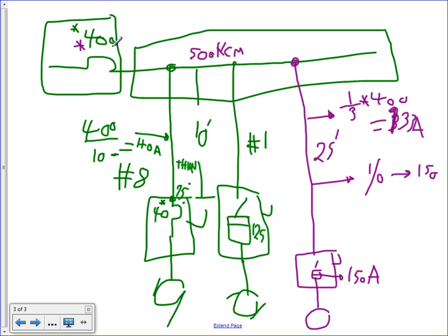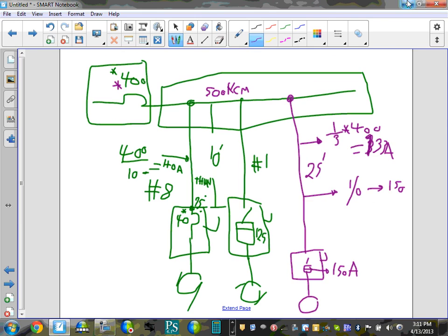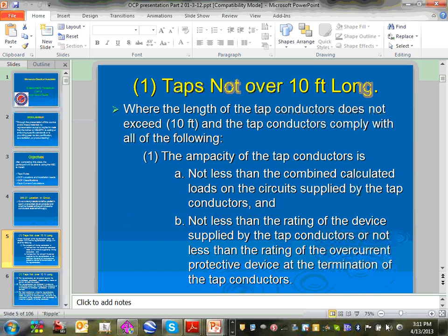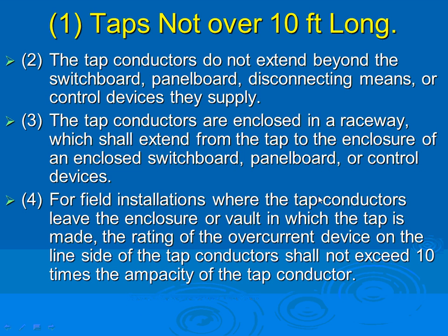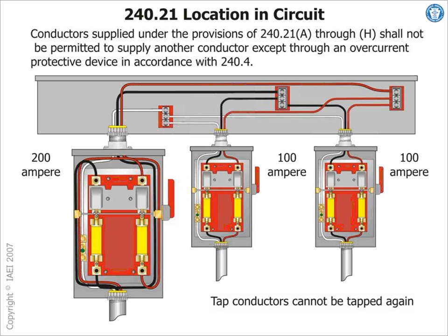Okay, so these are the tap rules, guys. So this is the 10 foot. Here's the 25 feet. 10 and 25 feet, the tap rules. You can see how you put the gutter here. Great opportunity to tap and feed multiple conductors. Makes sense? And it doesn't matter if you tap with a foot or with 2 feet.